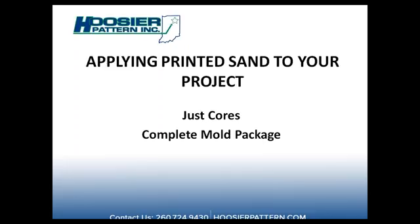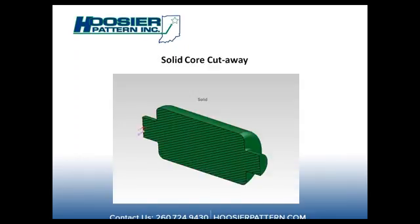So, are you going to need just cores or a complete mold package? Deciding what you need is one of the first things we're going to be talking about when you come to us. If you just need printed cores, there are 3 kinds of cores you can have printed: solid cores, shell cores, and hybrid cores. Now a solid core is as it says. It's solid through and through sand. You know what you're getting.